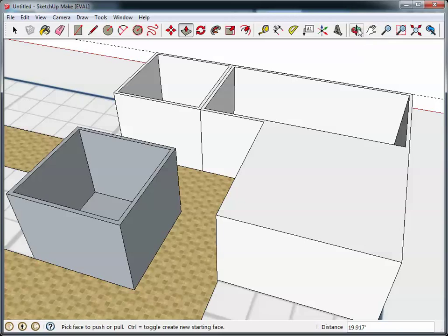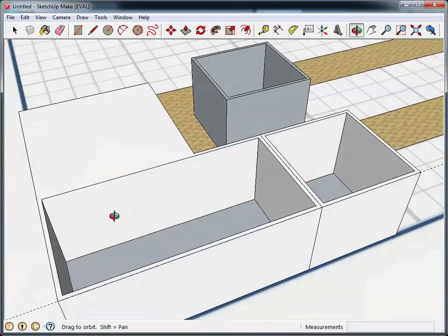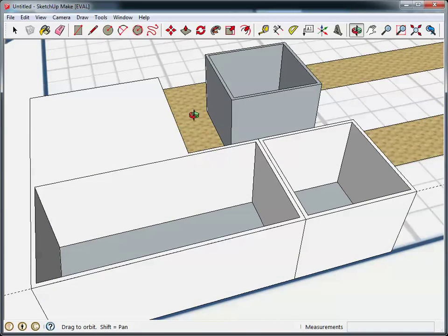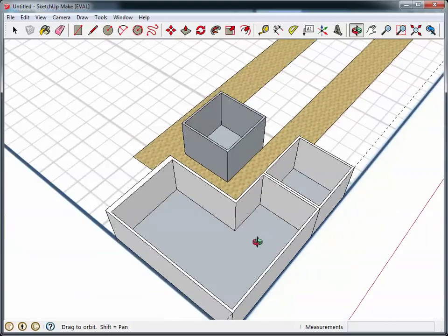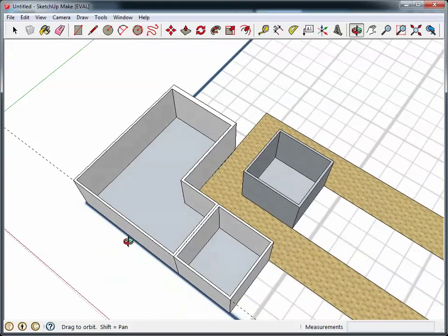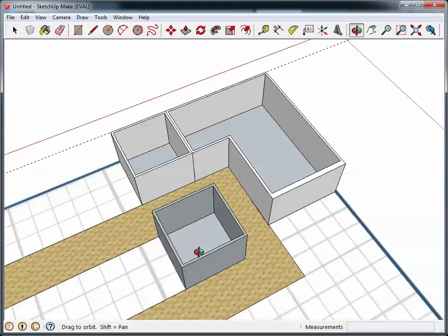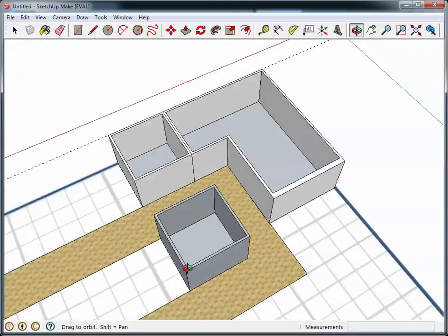So we want to orbit around over here, and then we'll also have to select something just short of that. What I mean by that is grab a rectangle tool, but don't go all the way to that point. We'll leave a little space here for a wall, so we can push that into this space like that. And you can see here we have kind of an L-shaped conference room or main office or Xerox room or whatever you have planned for the building.